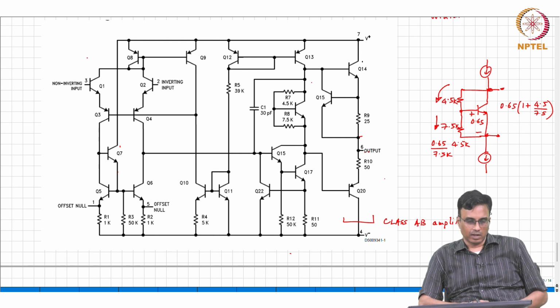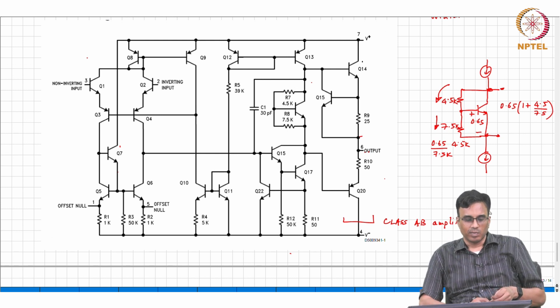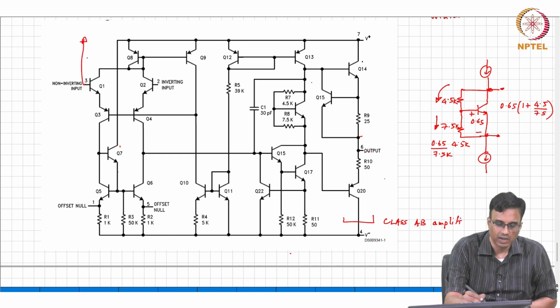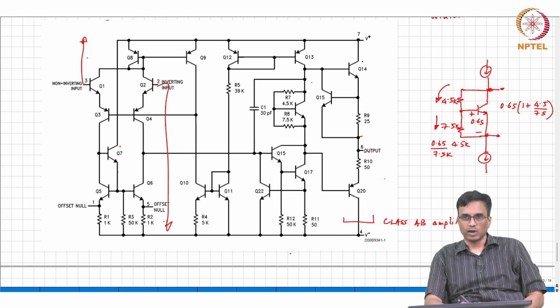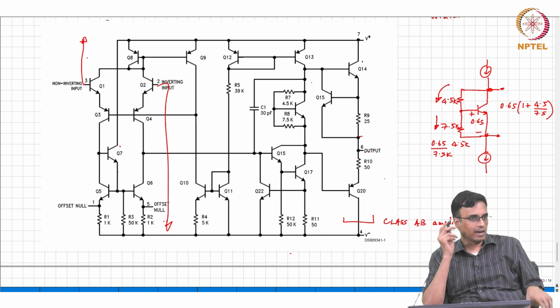And of course, there are some more bells and whistles. For example, another common thing people do is, by mistake, reverse the supply and ground, so there must be some protection for that. Then people will, by mistake, connect the input to VDD and this to ground, and you don't want your IC to blow, so there are some protection diodes to make sure that eventuality is taken care of.